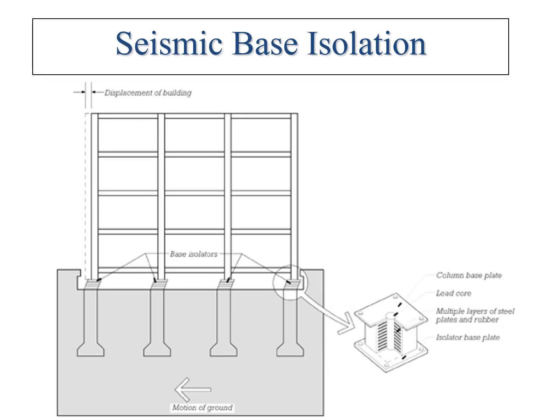So let's take a look at these one by one. Seismic base isolation. How is this accomplished? You can see there's these special connectors here that are placed down at ground level between the building and the foundation, that in that case would be a cast in place caisson.